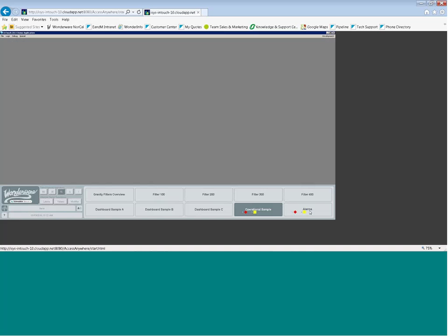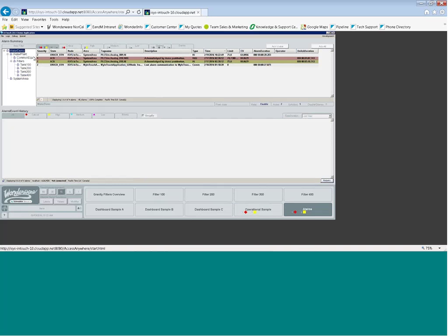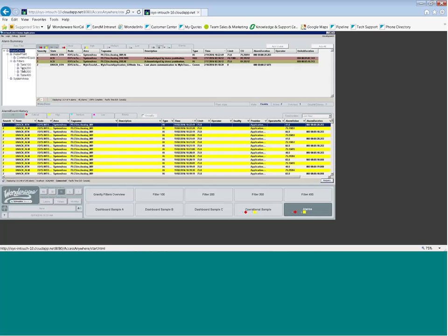And then what they could do is drill down into the alarm if they wanted to see the alarm display and get more information on what the alarm is, where it's coming from, sort by the criticality of alarms, sort by area in your plant, so I can sort by multiple areas to see the alarms in certain areas. I can acknowledge those alarms. I can shelve alarms.